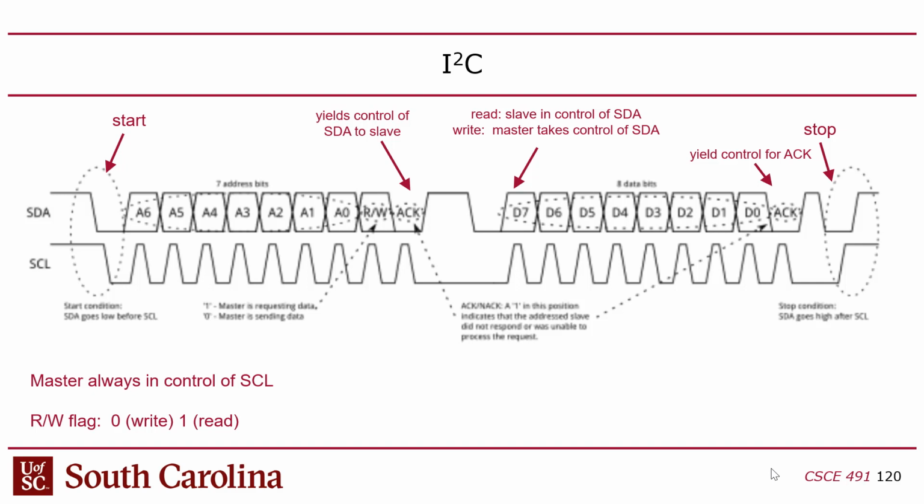It doesn't really matter if it's rising edge or falling edge, but the point is that it uses that change to capture data on that change, right? And then I mentioned that there is a setup and a hold time where you have to keep the data stable for a little bit before the change and a little bit after the change, right? When I say change, I mean edge, right? So that's edge triggered.